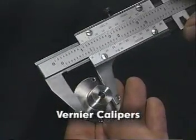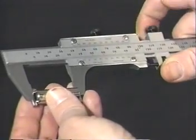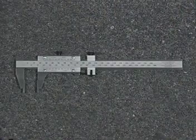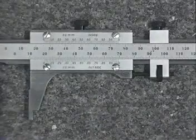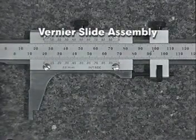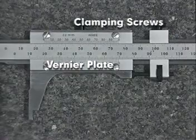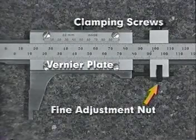Vernier calipers are graduated calipers that incorporate an additional graduated vernier scale for greater precision. Vernier calipers consist of a graduated stationary bar with a fixed jaw and a movable vernier slide assembly that combines a movable jaw, a vernier plate graduated into 50 units, clamping screws, and a fine adjustment nut.